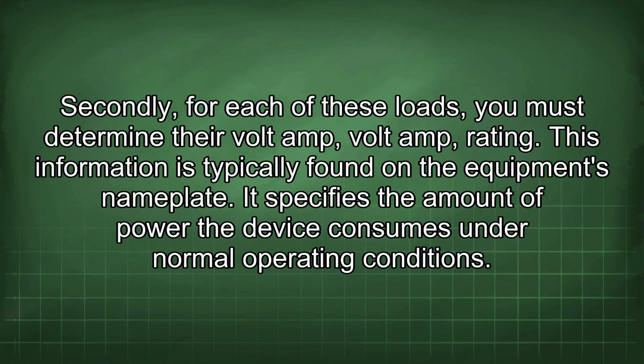Secondly, for each of these loads, you must determine their volt-amp rating. This information is typically found on the equipment's nameplate. It specifies the amount of power the device consumes under normal operating conditions.